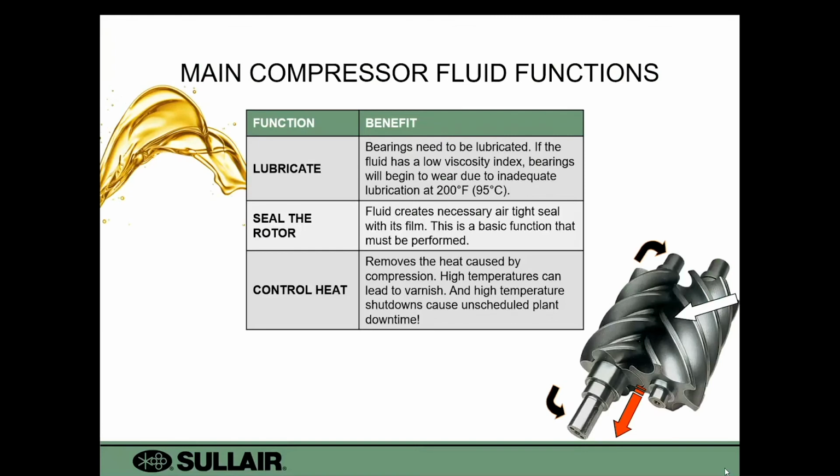There are three main functions of a compressor fluid. There's three main things it must do when it's in the machine. Number one is to keep your bearings lubricated. This is very important because that's where you want to make sure you avoid any bearing wear. Next is to seal the rotor. Without compressor fluid, you actually wouldn't create an airtight seal. It needs that film to compress the fluid.